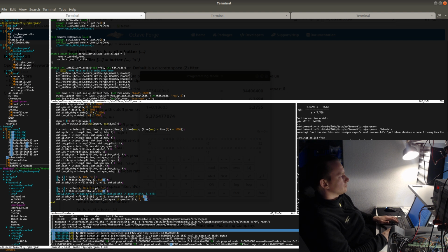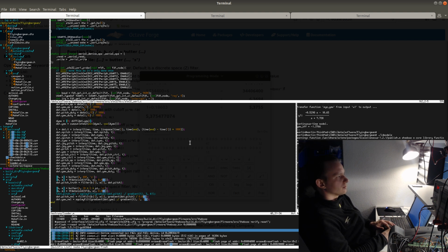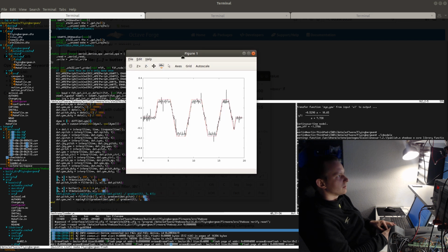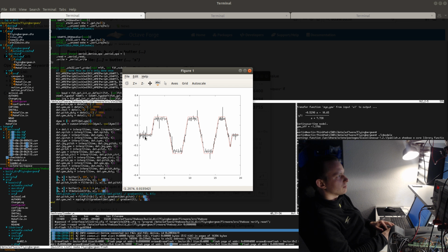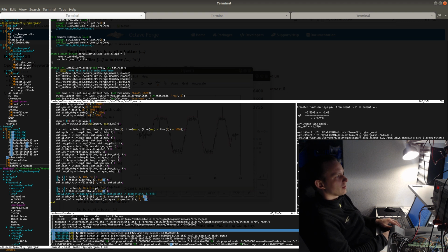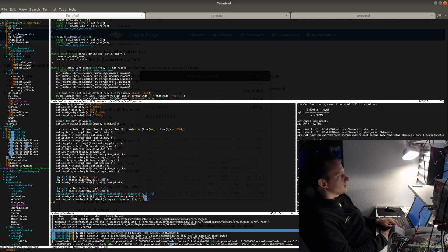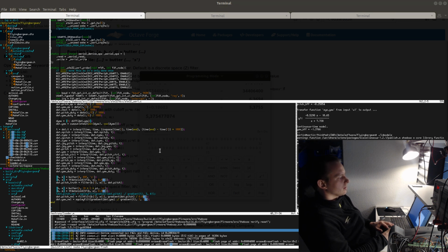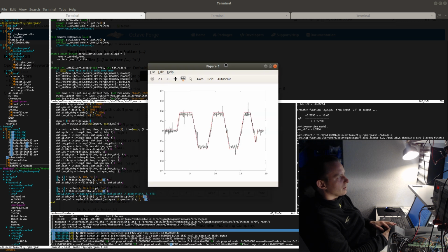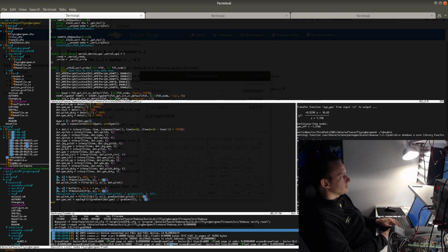And then let's see if we get a better true value. Yeah, so now I got rid of some of that phase shift. So I can make a better comparison between the transfer function and the actual measured data. So this is getting pretty close, and I could adjust the DC gain to kind of get this function to match the measured value better. So in this case, we can make it a little bit lower.